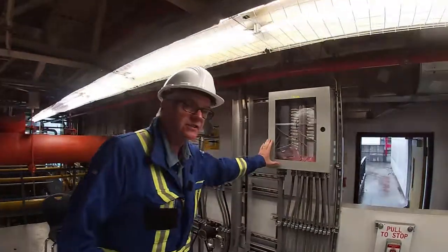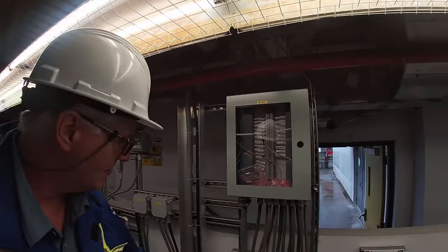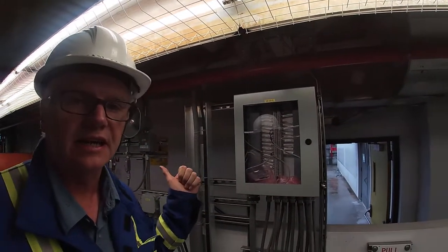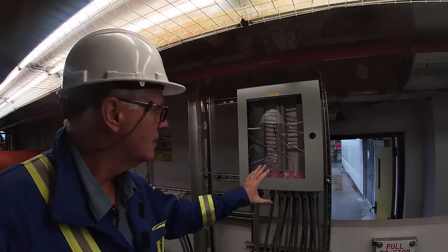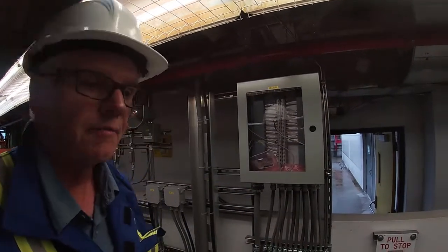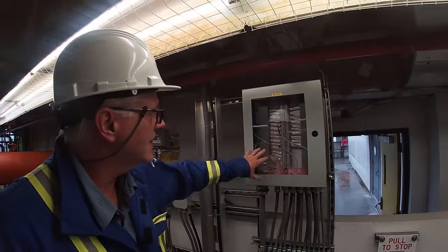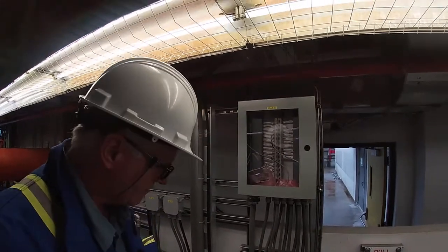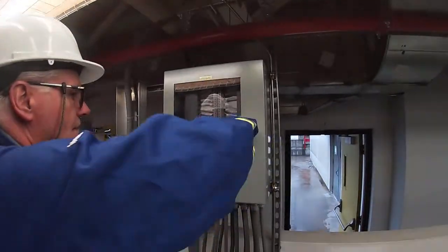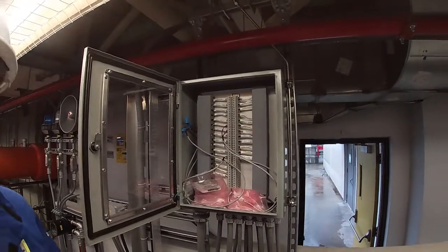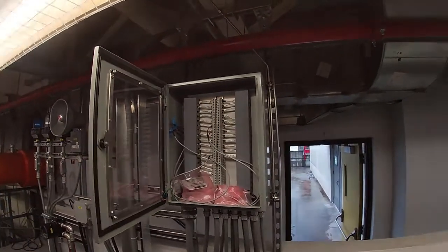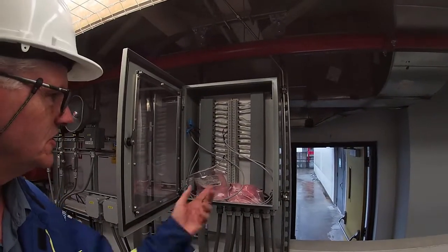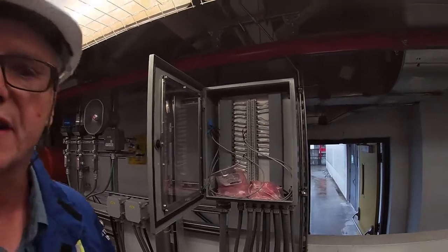This is our junction box here. All the cables came through this multi-conductor that was pulled into our SIS DCS cabinet down below, and from here we go out with the individual pairs to all the devices. You see that I have some wires hanging in there. The reason I did that was, and I'll open it up, so if you wanted to do a calibration on one of the gas detectors, I can hook up a communicator here. It's just easy to do it here instead of having to open up the cover.